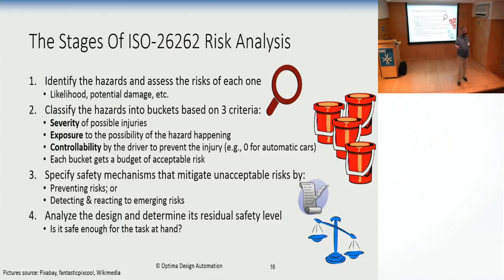Some of it is similar to manufacturing testing, like hard errors, like stuck-at faults. Some are the soft errors that some people I know are working on, where radiation can flip a value, and then the part continues working as usual, but with the wrong value. You need to think about all the hazards, and for each one, decide what might go wrong about it.